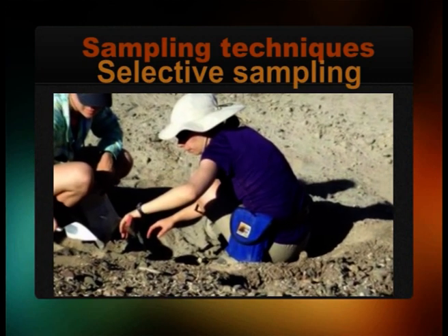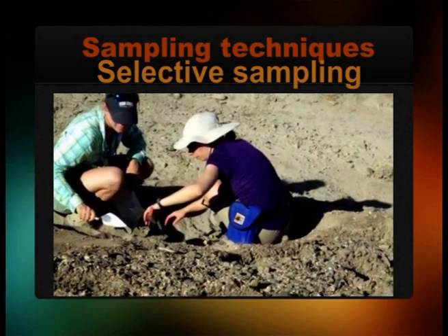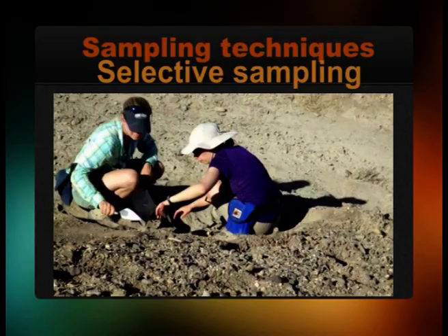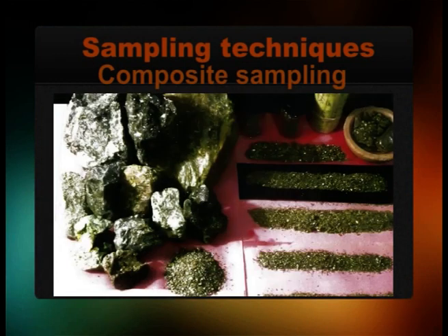Tenth is composite sampling. When samples are collected at frequent intervals at a station, analysis of each individual sample would be prohibitive in cost and for many streams would result in needless duplication. Consequently, the compositing of several samples into single samples for chemical analysis is a common practice, but it should be avoided whenever possible.